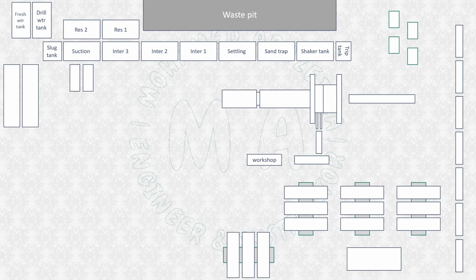The rig layout should be something like this. The dimensions of everything should be included, but I removed them so the image can be clear. This is a base drawing. You can consider it 0.00. Everything is aligned around the subbase, and every single dimension should be relative to the well. This makes putting proper spacing for the equipment easier.